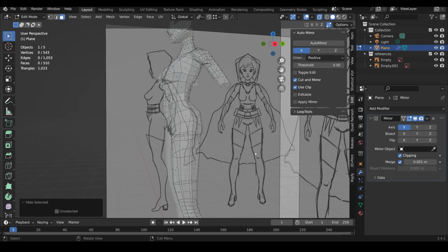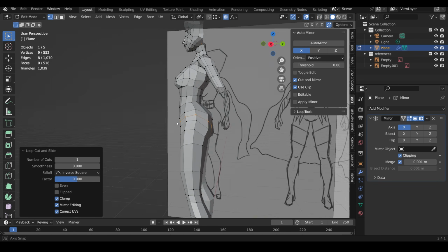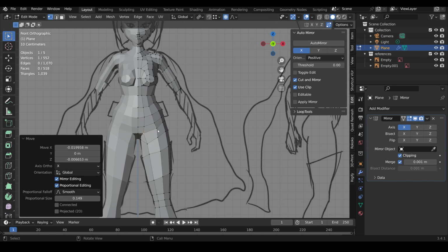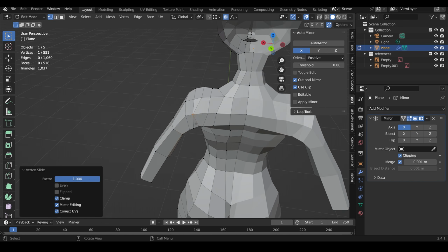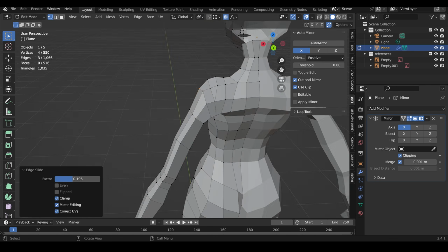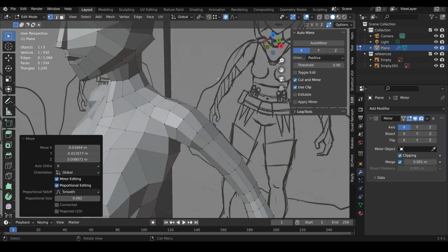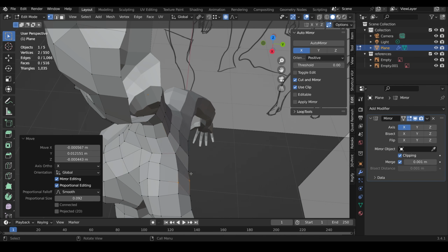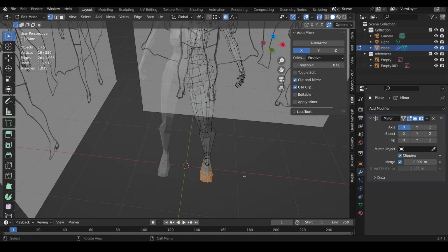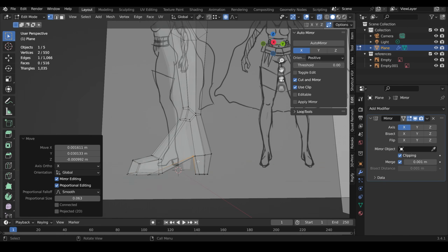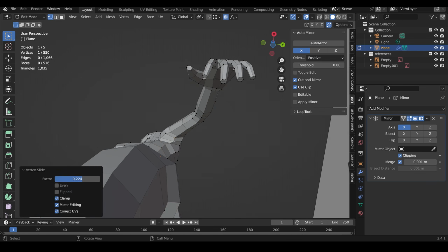So at this point, you need to go over your mesh and make sure things are working, lining up with the reference images. You might need to add a bit of topology in places. You can see I'm working on the buttocks area here. I use the smooth vertex tool quite a lot at this point because it smooths out all the vertices. It tries to kind of put them into a sphere. Just select a group of vertices, go up to the vertex menu and choose smooth vertex. And I like to put that into my quick favorites. And you want to have a good check that things are kind of rounded. There's nothing sticking out where it shouldn't be. Lining up the vertices in the feet to make sure they're flat on the floor and things like that.